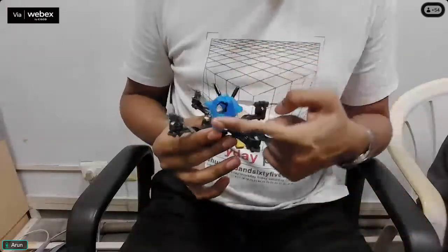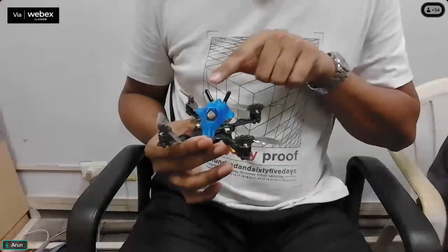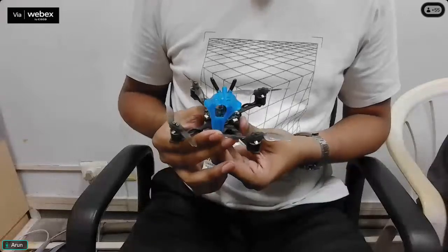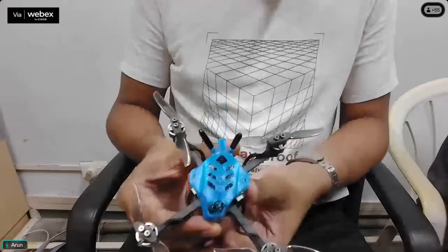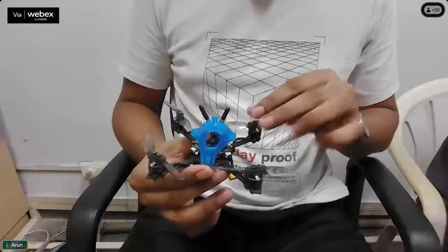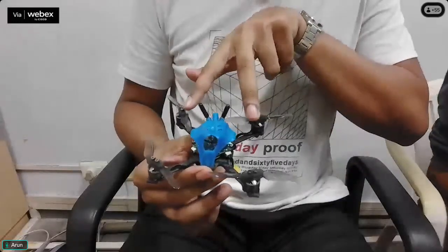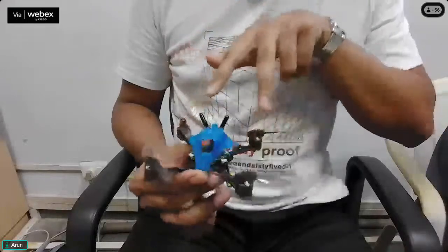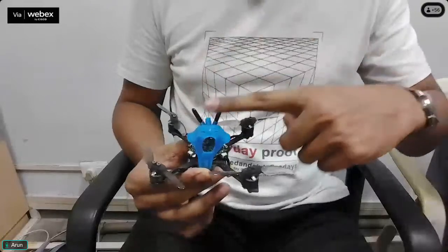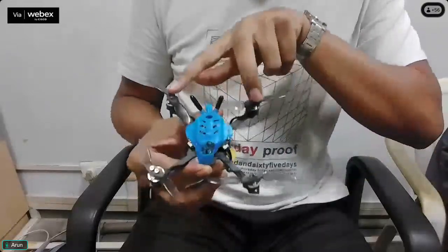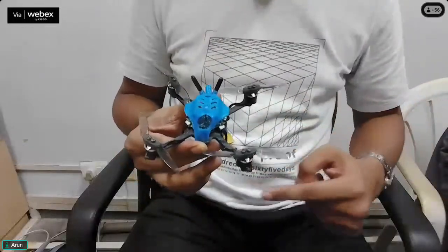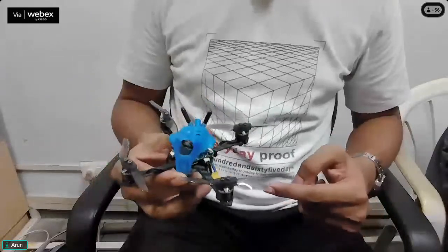So this is the front of the drone, and this is the back of the drone. When I am doing a pitch, the drone will tilt like this and go like this. This is the pitch motion. When I increase the velocity of these two rotors compared to these two rotors, because these two are rotating at a higher speed, there is a torque like this, and the drone will tilt in the y-axis. This is the y-axis. The drone will tilt like this, and that's how the pitch motion is achieved.